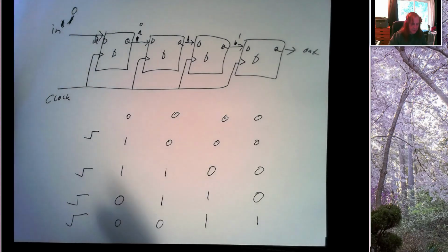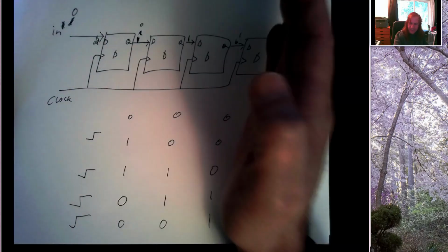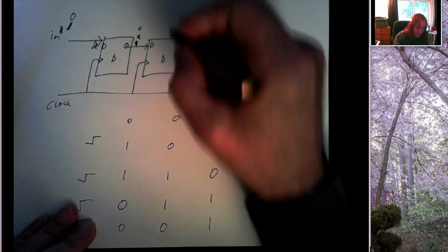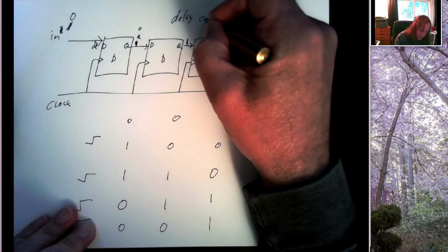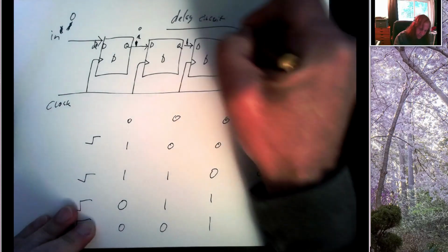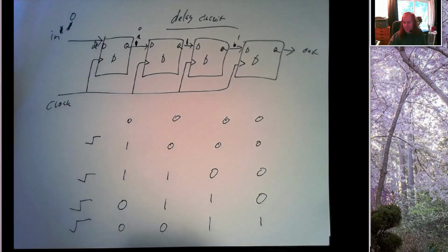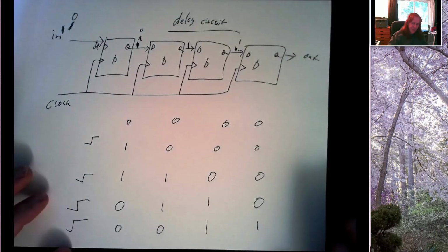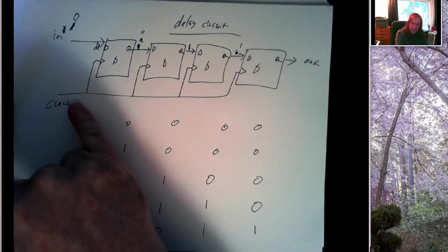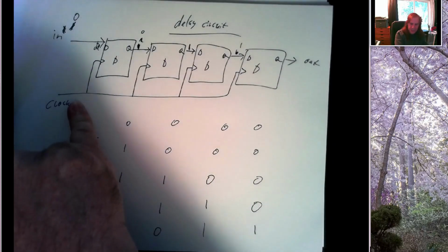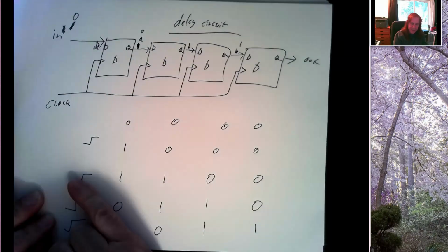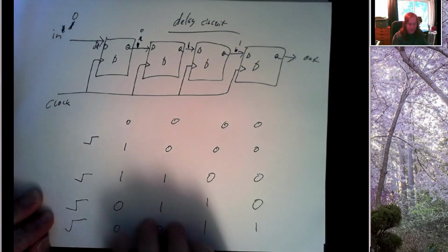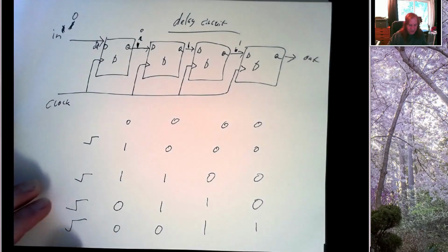So this is a shift register. We have something coming in the beginning, and each time the clock ticks it moves down one stage at a time. This is also how we can make a delay circuit. We use a simple version of this in Lab 6 to make our 2 to 4 second delay for the yellow light of our traffic light. It was just a pair of flip-flops, and we drove the clock from a 555, 2 seconds for each clock tick, and each time it ticks our input value moves down, and so we had our old green and our delayed old green signal coming out like this.